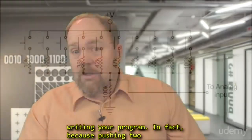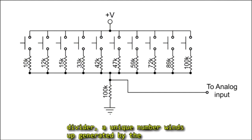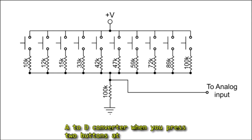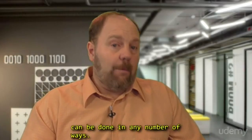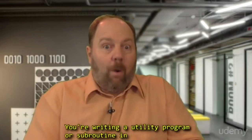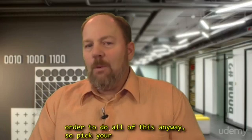In fact, because pushing 2 buttons at once will make a unique complex voltage divider, a unique number winds up generated by the A to D converter when you press 2 buttons at once. So you can have multifunction buttons. Now, also bear in mind, how you read that information can be done in a number of ways. You're writing a utility program or subroutine in order to do all of this anyway.